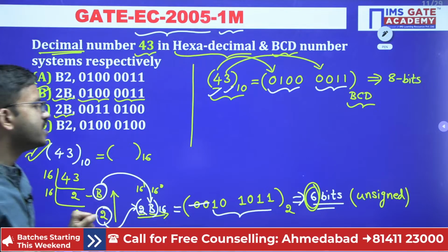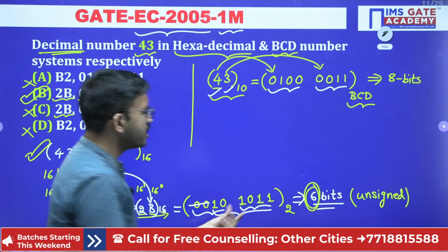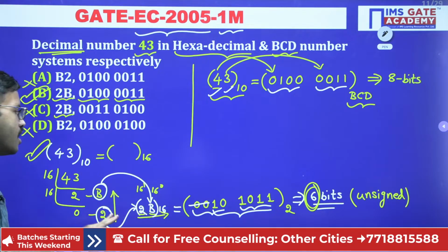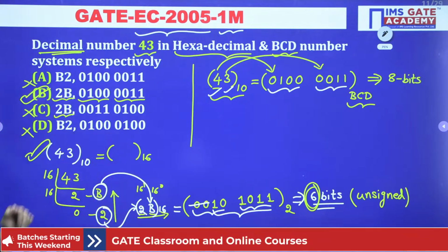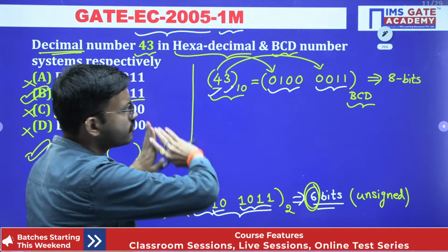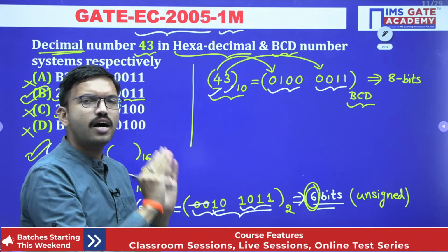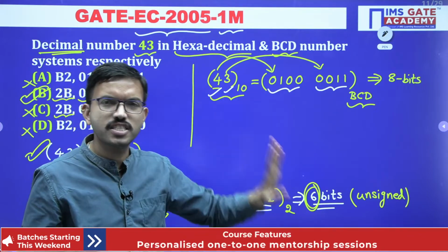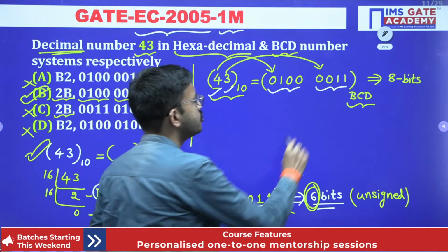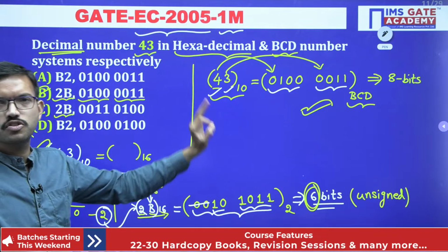Whereas here, if you do the grouping of 4 bits, you will get the corresponding hexadecimal digits. From here, you have to convert into decimal. That means a 2-step procedure is there. That's why whenever after performing any mathematical operation, if you want to display that result in the decimal form on the 7-segment LED or LCD, if this frequency is more, that time better you can use BCD code. Okay, so that is the reason why we are using BCD.